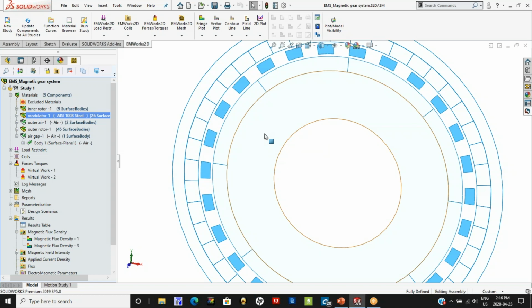With the modulators, we can keep a sufficient air gap between the two gears, and it can still function well. This is really the job of the modulator. In some designs, you won't find the modulators, but in that case, the air gap is minimized, giving it a very tight tolerance, and your manufacturing capability must be equipped to handle such tolerances. So usually in large gears, you do find these modulators.